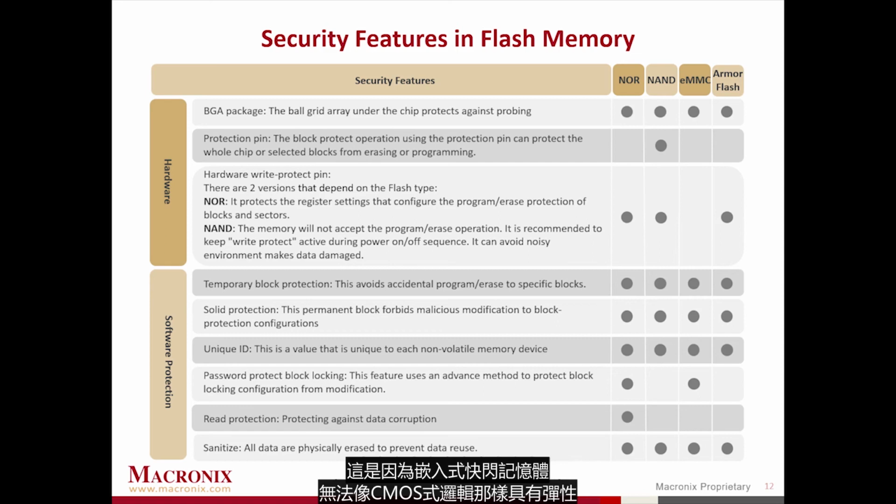This is because the embedded flash doesn't scale like CMOS-based logic. For example, 40 nanometers is the current stopping point for embedded flash, and so expected overall die size and cost reductions fall short. Also, customers have varying density requirements, so betting on any given customer memory footprint requirement is risky. And embedded flash adds cost to the product that could be shifted to the customer.